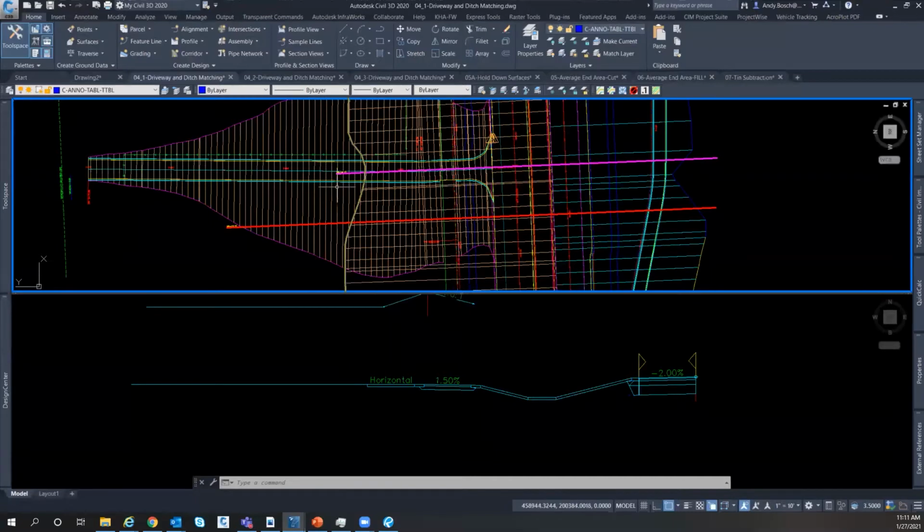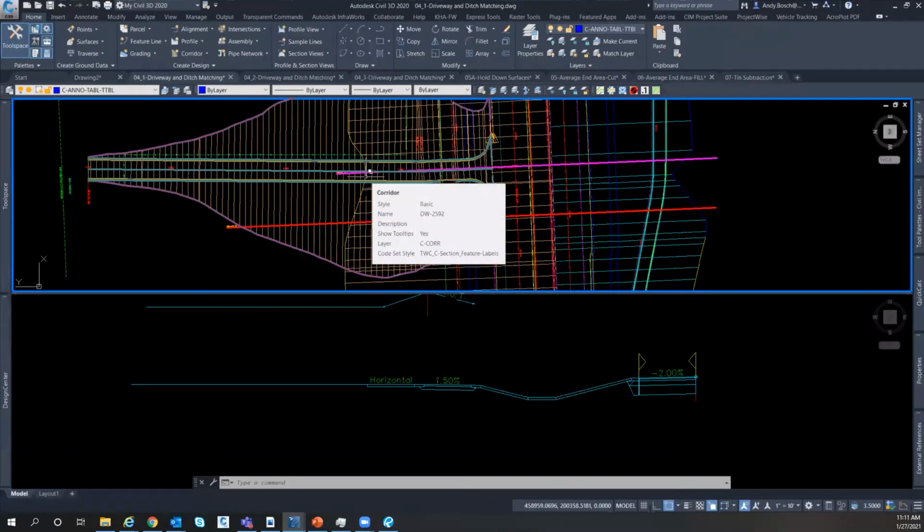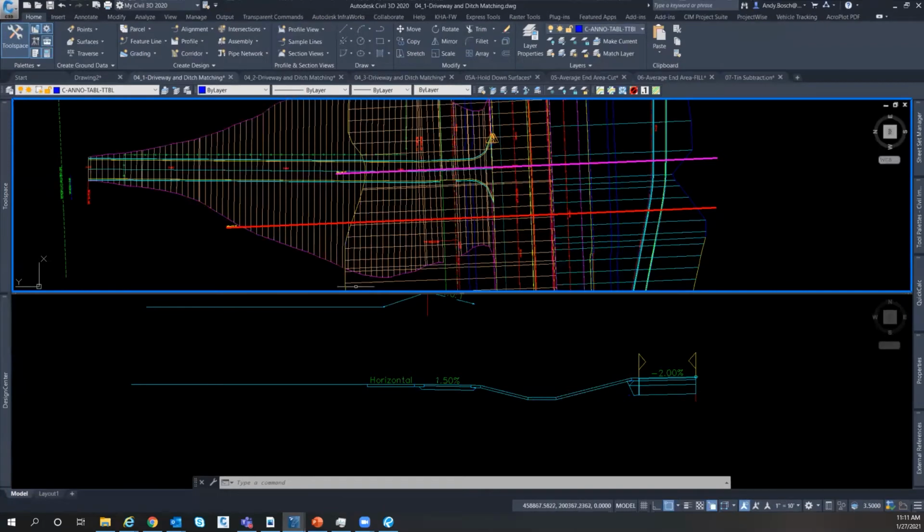if I didn't have that surface where I built this corridor here, if it's not perpendicular to this point, if there's not a surface underneath here, since it pulls back in due to the grading of the slope, it's not going to be able to find this point. So I have to make kind of a dummy surface that runs all the way out to here.